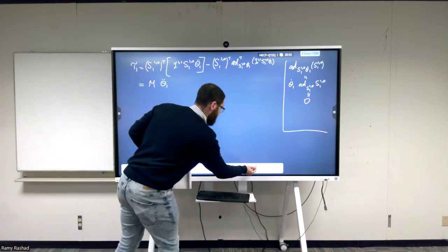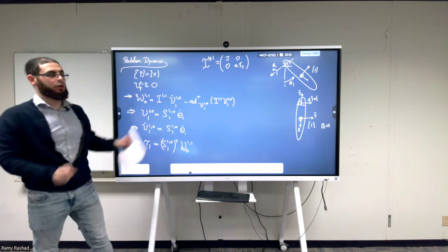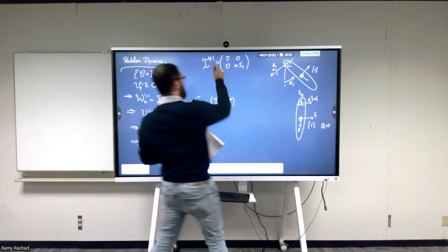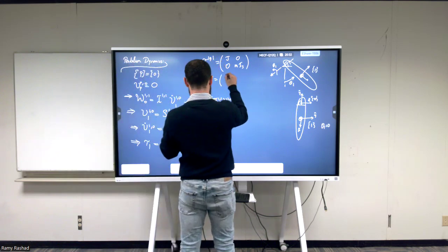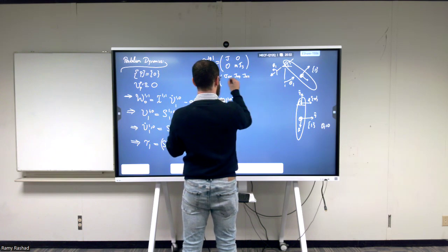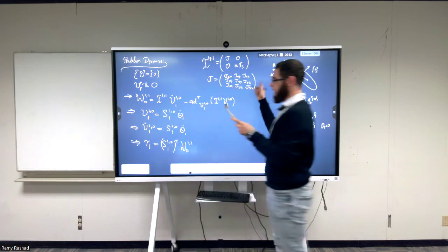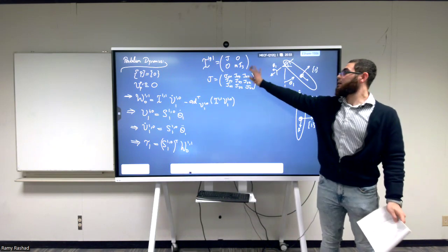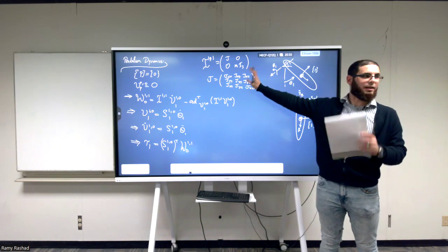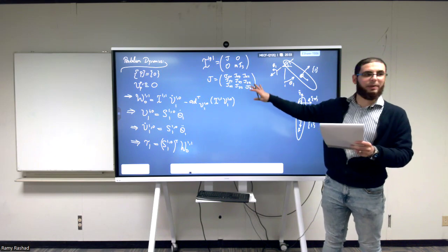If you take this expression of the I, it's something very easy to play around with. Expand the J such that it looks something like this: Jxx, Jxy, Jxz, Jyy, Jyz, Jzz, and so on. Expanded like that. What I'm trying to say is keep this completely populated. Don't assume it's diagonal or anything. The most general thing. Of course, it's symmetric. It has to always be symmetric. So keep it like that.